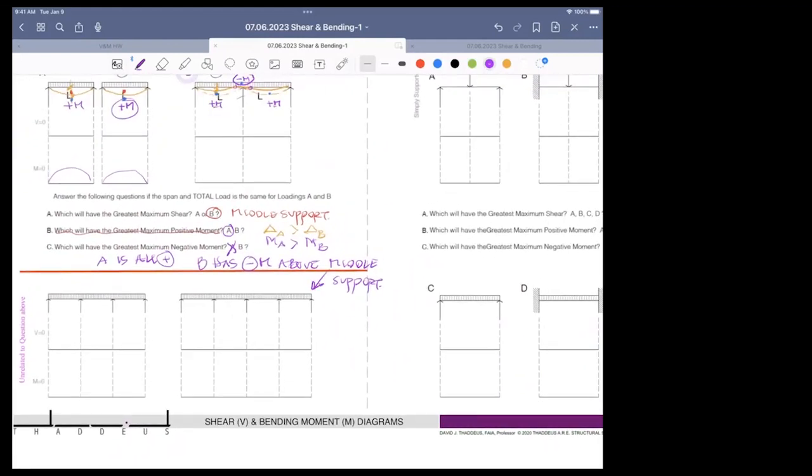Where's the maximum shear for this loading? We just did this. It's the reaction. I don't know what the shear diagram looks like. It looks like this, although it's complicated, but the maximum shear is at the support. It's equal to the reaction. And the moment diagram, oh my God, this is difficult. This is negative, this is negative, this is negative, this is negative. It does something funny. Zero shear, zero shear, zero shear, zero shear. It's going to do something funky. It doesn't matter. The concepts are the same.